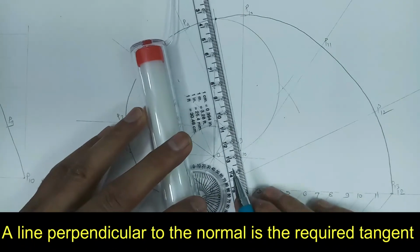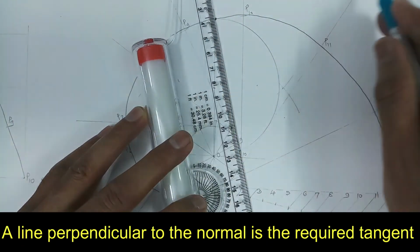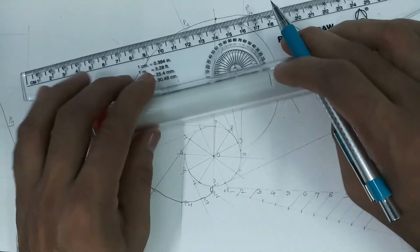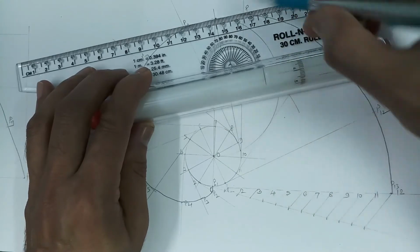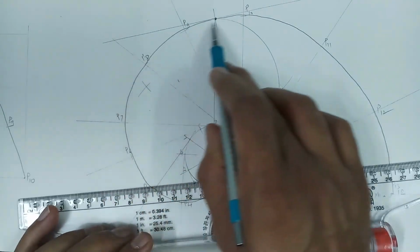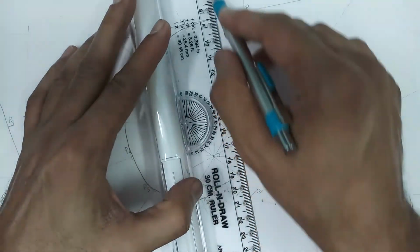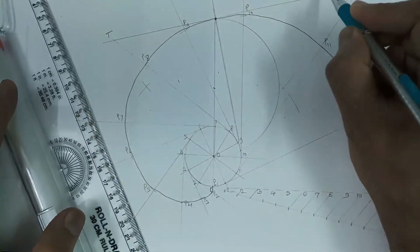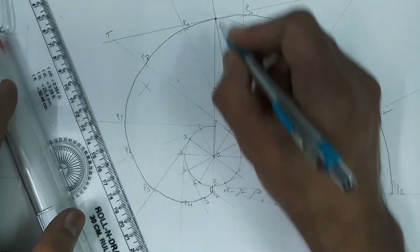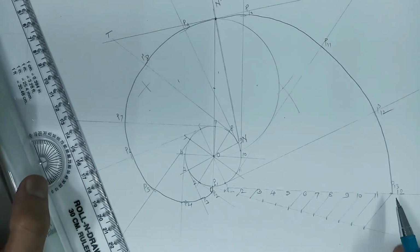Now, if you are using a drafter, with one scale of the drafter on this, the other scale will give you a line perpendicular to this. If this is the normal, the line perpendicular to this will be a tangent. So through this point we have to draw a line perpendicular to this. So this is the required tangent and this is the required normal. Generally we name the tangent as T dash and the normal as N dash. So this is the way involute of a circle can be drawn.